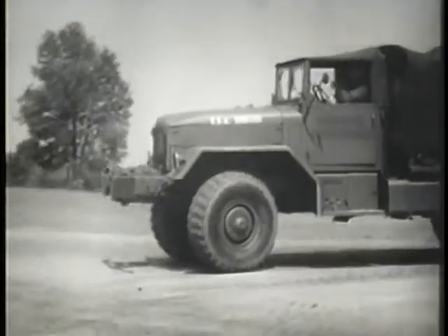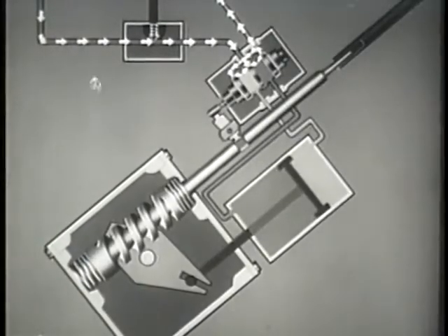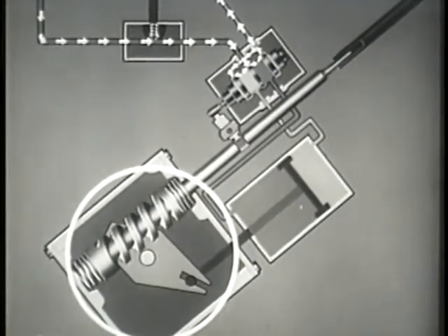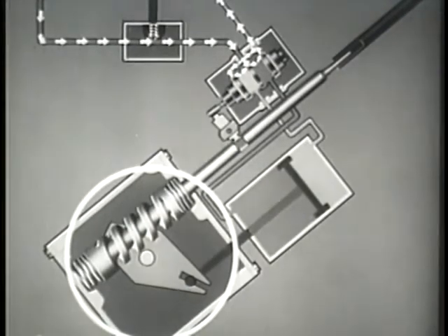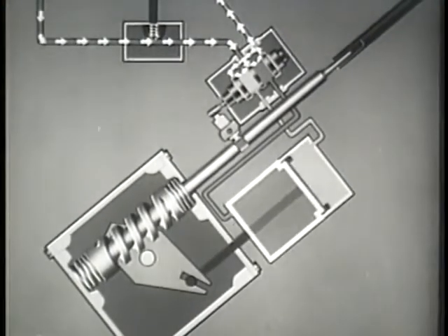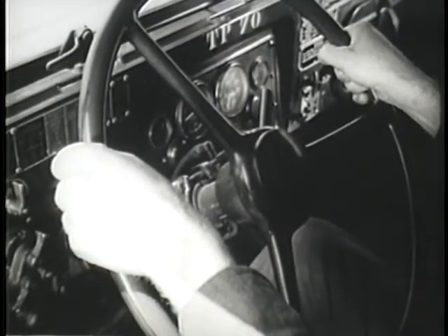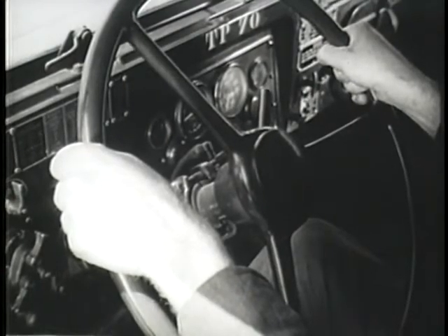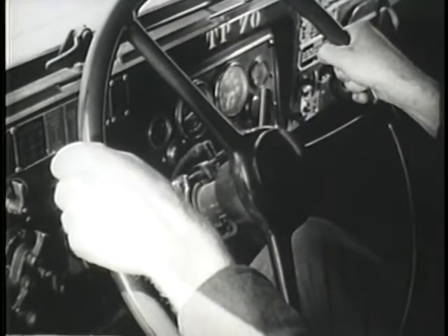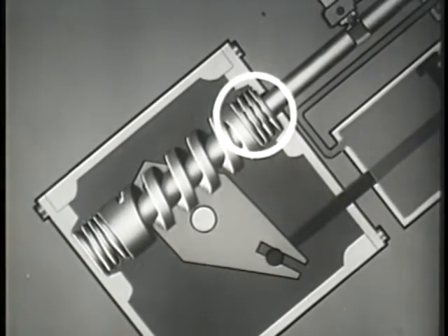When the front wheels are held in a constant turn, the cam will not be rotated. The Pitman arm shaft lever is held stationary toward one end of the steering cam by the increased pressure on one side of the piston. The tendency of the steering geometry to return the wheels to the straight-ahead position is overcome by the driver, who maintains a constant force on the steering wheel in the direction of the turn. These two opposing forces cause the steering cam to partially compress the upper cam spring.